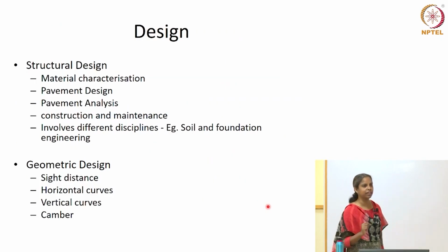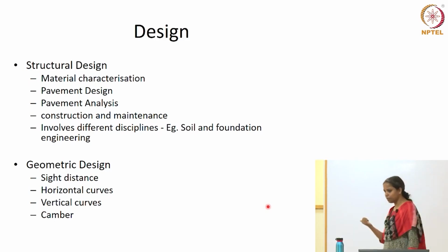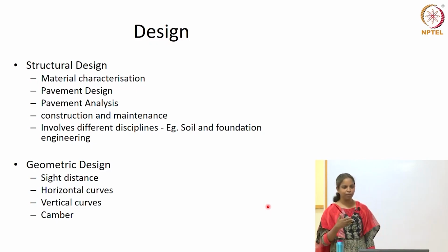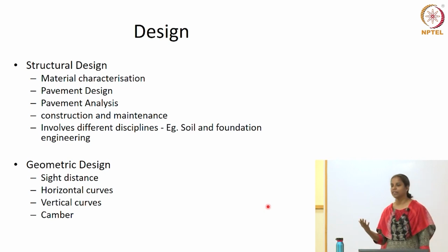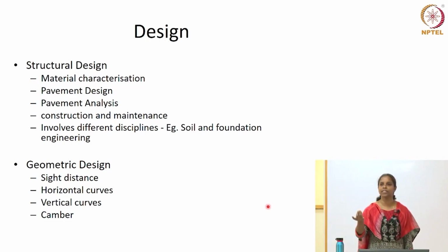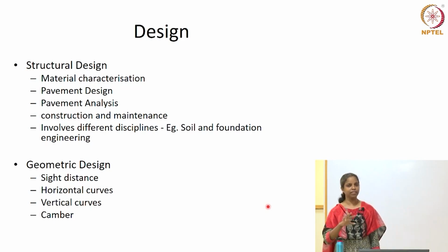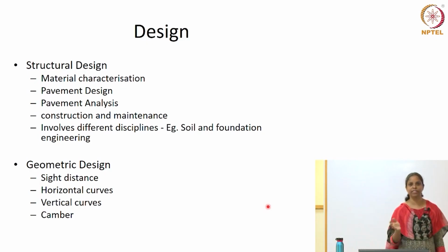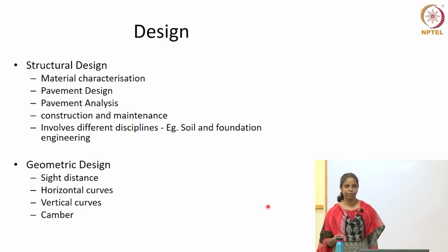So there you are looking at how do I design this system or the roadway. You will be getting into what I said as the hard side of it. Basically you are looking at how do I do the characterization of the material, how do I design the thickness, how do I check the stress and strain that's generated, whether it is safe, whether it will crack, all those information you need. So this is more of the structural design of the roadway. You would have heard some lectures on structural design of buildings. Similar to that, we are talking about structural design of roadways.